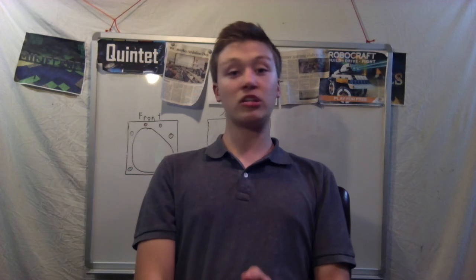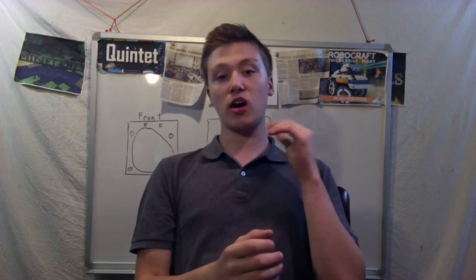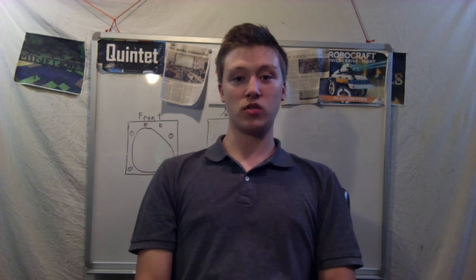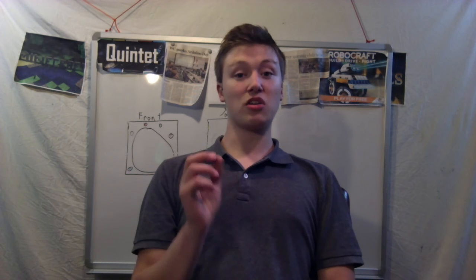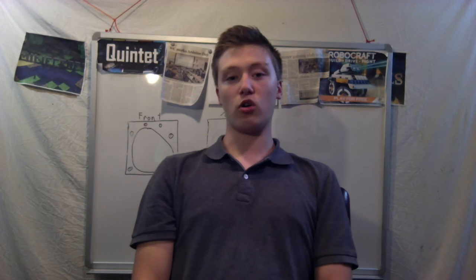Today we covered digital write. We did a little bit of digital read, and talked about that if then else statement just a little bit. We're not going to worry about that too much in this video. That's the next video. And we talked about analog read. Talked about analog write a little bit, and why we don't see that too much. You're going to know why, and what we use instead of that. We actually use the PWM pins on the Arduino. We use those with a different command for an analog write type of idea.